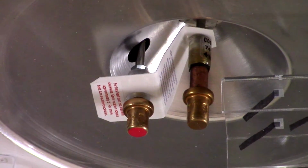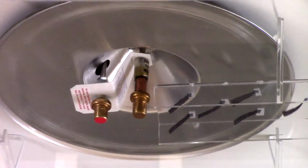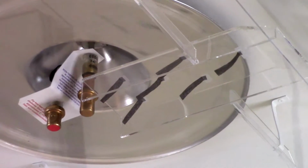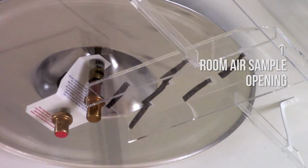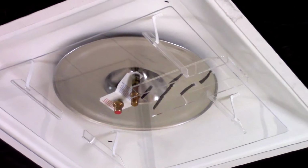Room air is induced over the thermal actuators by a simple yet highly effective induction wing. A small amount of supply air passes through a louver in the diffusion damper. This air is diverted off of the induction wing back into the supply air path. This creates just enough negative pressure to cause the induction of a continuous sample of room air to be drawn through the opening on the induction trough located at the leading edge of the face panel.